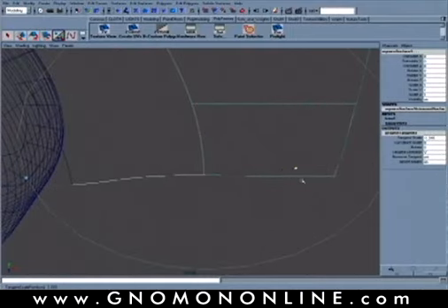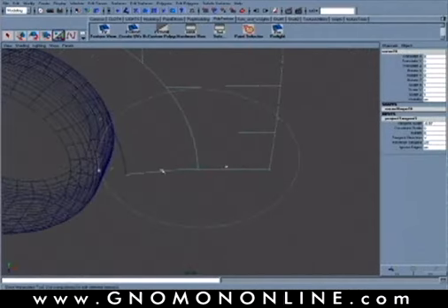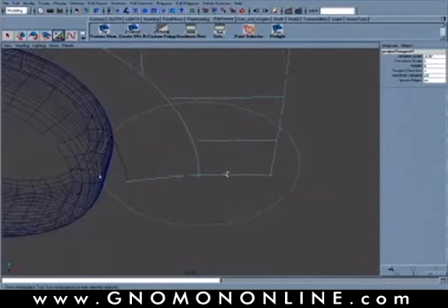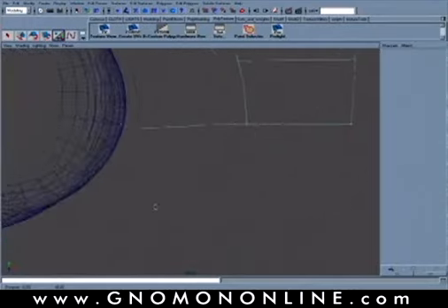So we want to go in this direction and then scale it out to how far you really want that tangent to take place. If you would look at, say, the CVs of that surface, when you're moving the tangent scale, you're really just moving that second point away from the end of the curve. So it's just pulling it along that line of tangency. Okay, so we can line up one of those there.